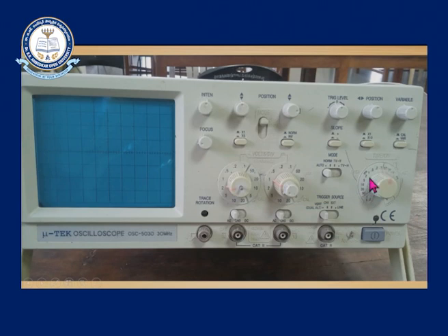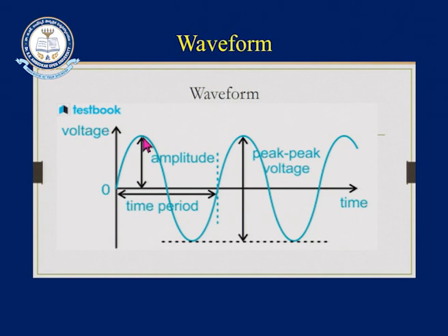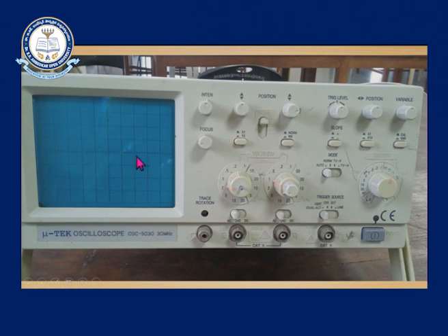This is the numbers there. For example, here in the waveform, from this peak point to this point, the distance is, for example, 3.2 centimeters or 3.22 centimeters. This value is noted. Then, how much is the time per division, for example 0.2? That value is multiplied, and you calculate the time for division.